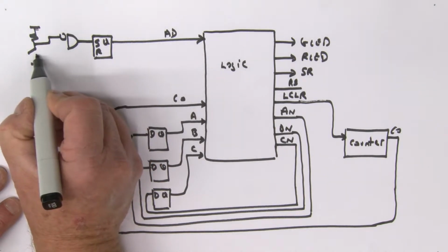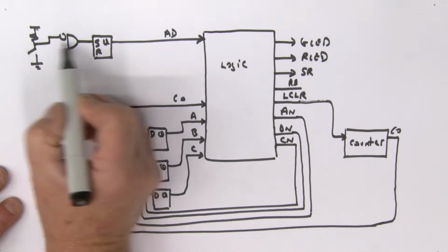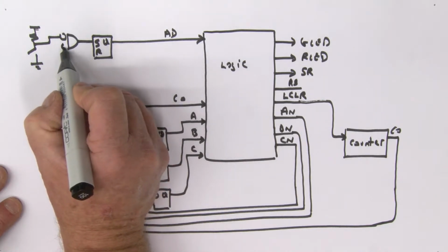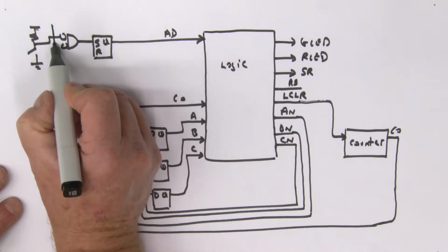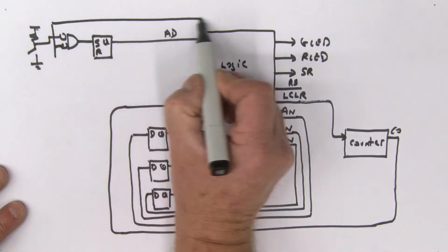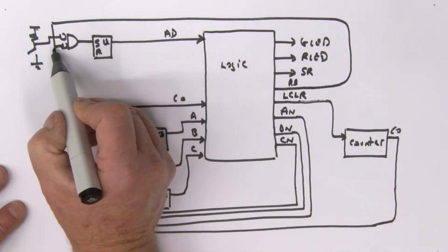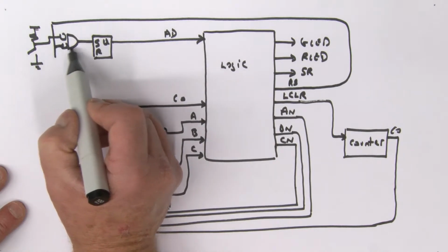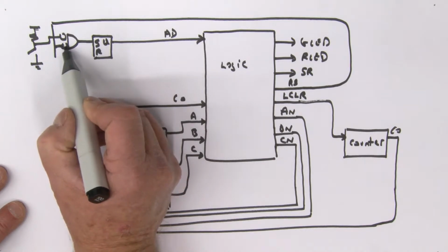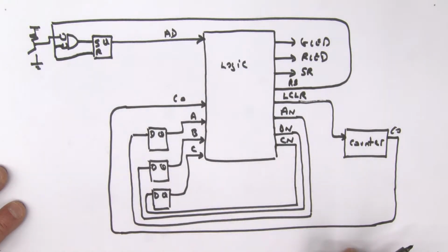And so if this is a normally open switch, remember that logic level there is a 1, but we don't want to set this thing. That's why we've got the inverter sitting there. And as far as the reset is concerned, remember we're actually bringing a reset line down like so. So this is my reset. Let me show you that. I'll bring that all the way from right here. So if the reset is true, if reset is 1, then basically we're forcing S over here to be a 0. Okay, so that's the purpose of that inversion before we go into the AND gate. And then of course the reset comes in like so.